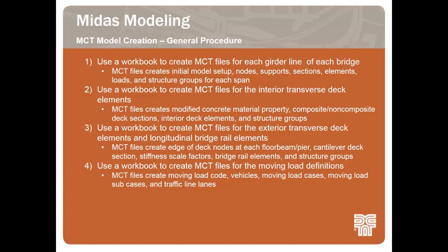The MCT file for the individual girder lines created the initial model setup, including nodes, supports, sections, elements, loads, and structure groups for each span.